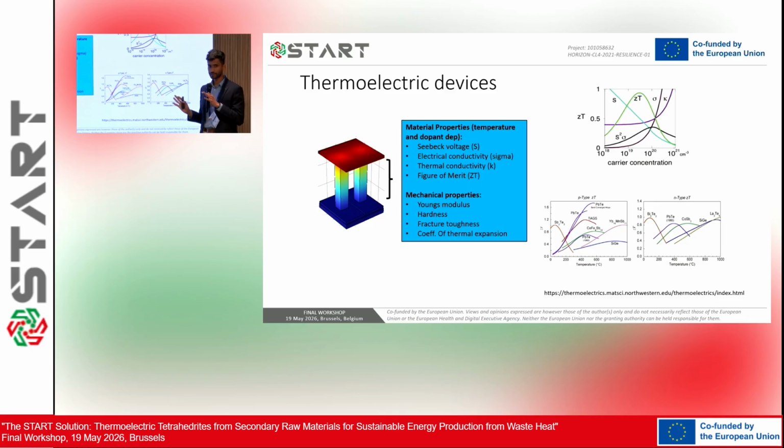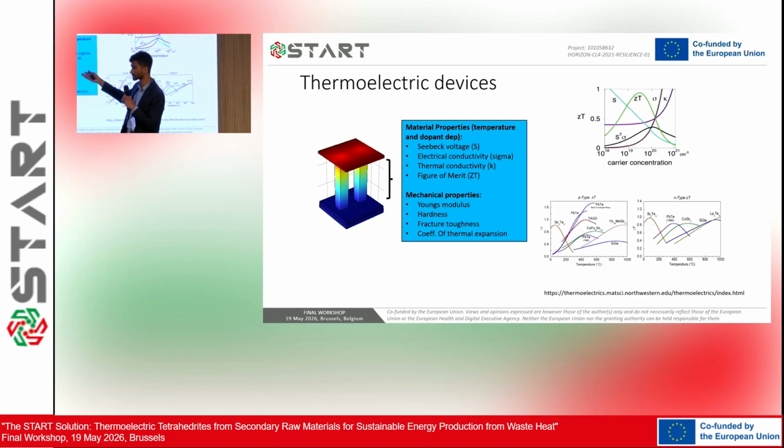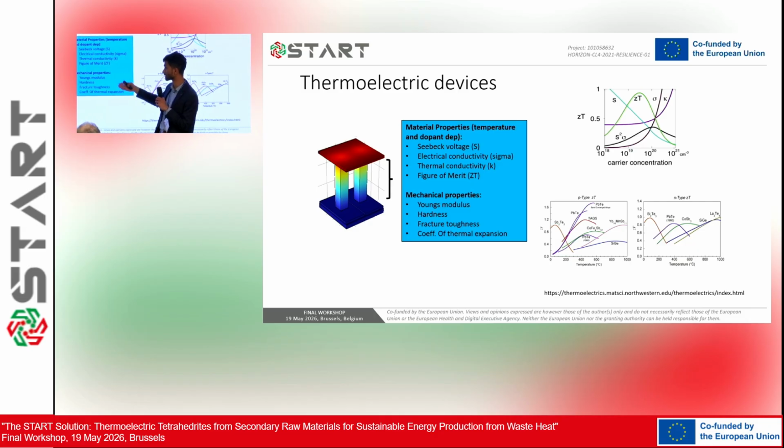This is a bit of a recap of what I had shown already in the previous workshop, explaining that when you're modeling a thermoelectric unicouple in a device, there are many aspects that you have to take into account. There's not only the material properties that Patricia touched upon, so the temperature-dependent thermoelectric properties such as Seebeck, electrical conductivity, thermal conductivity, but also the mechanical properties, because these devices have to actually go into something, right?